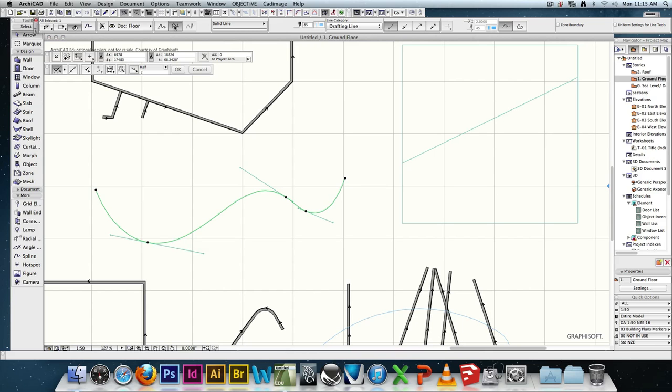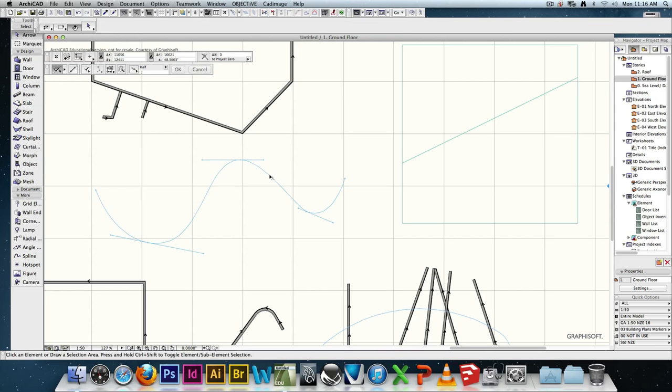Very similar to a flexi curve. However, see this one here, this one has what's called Bezier handles on it. So what that's saying is that this kind of controls what's happening at the tangent. When I say tangent, that line is parallel to the curve at that exact point. These little things that I'm pulling out from there are dictating how that curve arrives at that point and leaves that point. So, in theory, I should be able to create a perfect circle with 2 points.